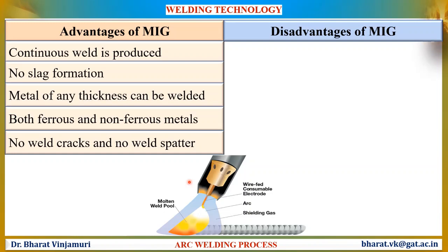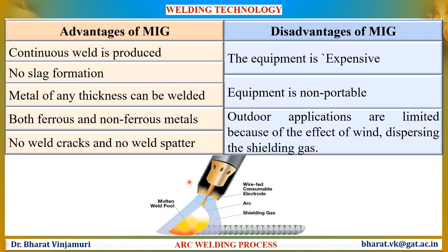Let us now see the disadvantages of this process. The process is expensive, and the entire equipment is not portable. This process is not suitable for outside applications because of the effect of wind. The wind may disperse the shielding gas.